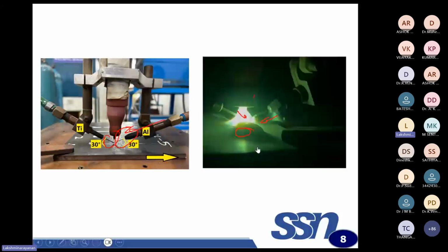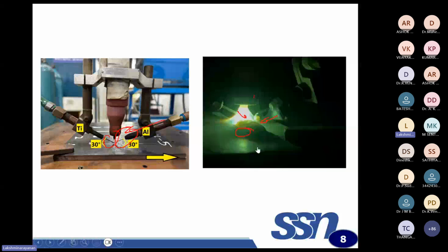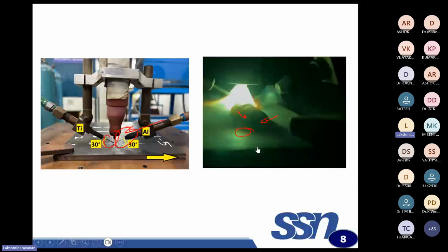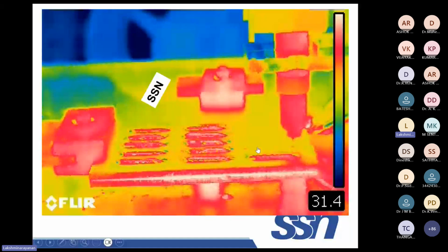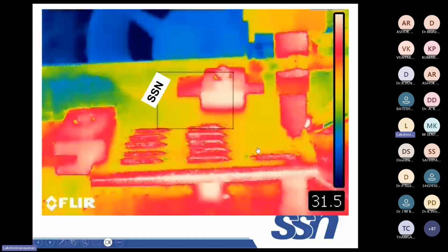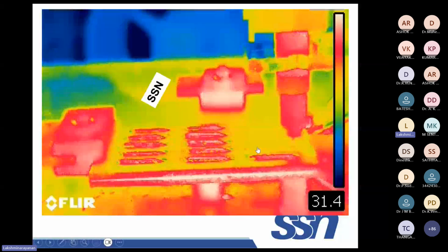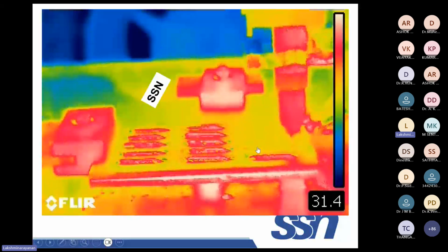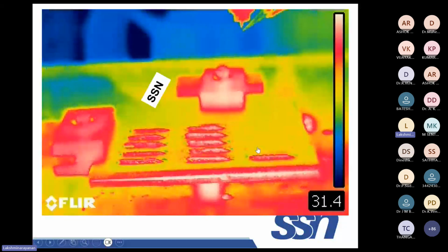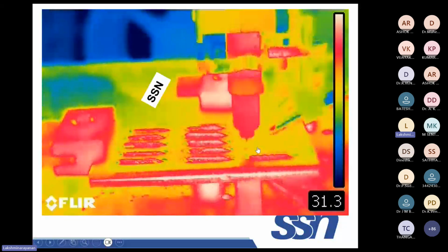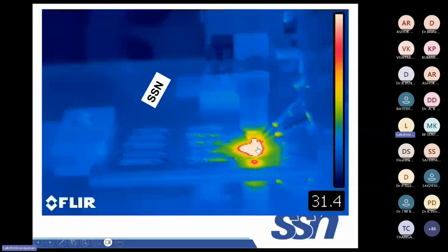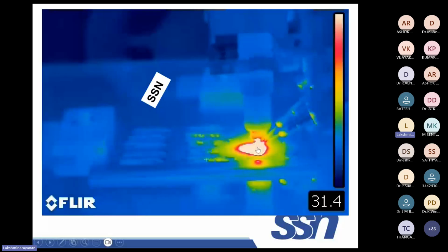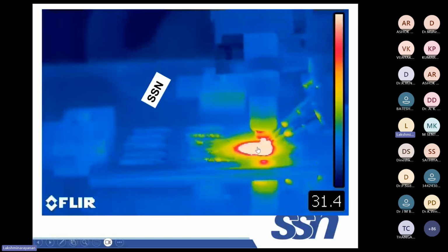This is the thermal imaging we did. You can see the torch is going up, robotic system. Once it reaches there, we can directly record the temperature. You can get cooling curves from each and every point, starting from this point, the wire and this melt pool, and just around the areas, you can construct the heating and cooling curve from this.